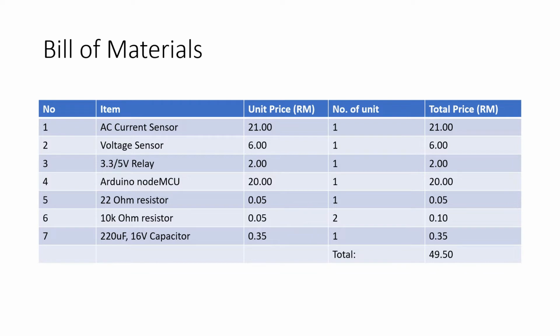For the AC current sensor, it's rated for 100 ampere, which means if we use it at a low power place, we can buy a lower rating one. In the end, this means the bill of our project is very flexible. Lower power means lower cost.